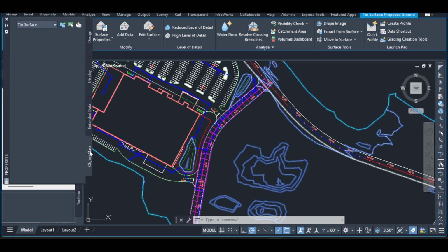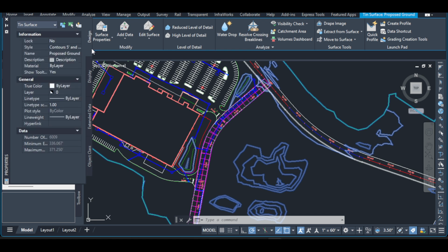You'll be prompted to select the boundary object in the drawing. Now select a closed object that will serve as your boundary. A polyline or a feature line works great as long as it's closed and clean. If a polyline is open or has tiny gaps or overlaps, fix that first so the clip behaves reliably. Using a clearly named layer for your boundary and keeping it visible can also help you manage edits later.